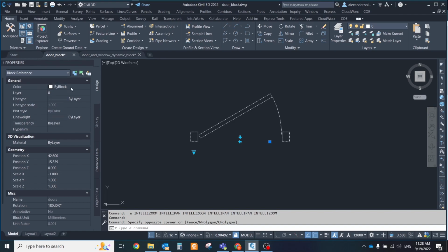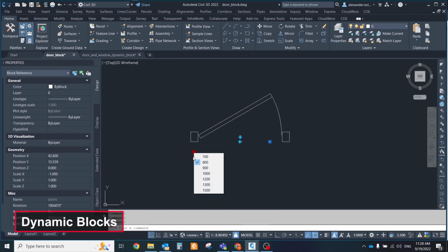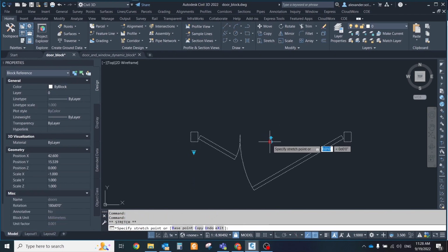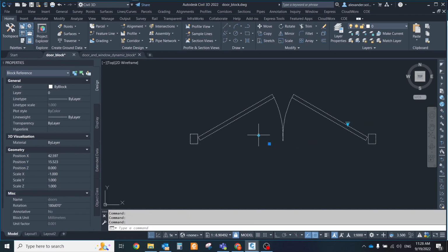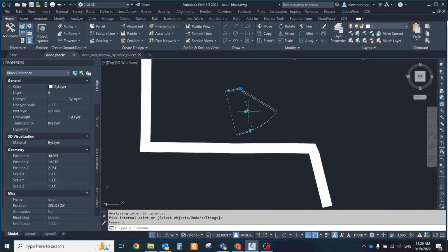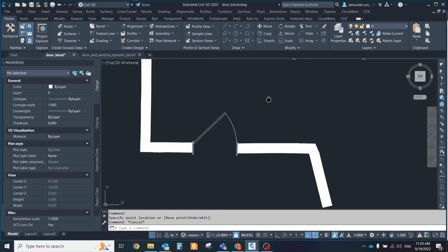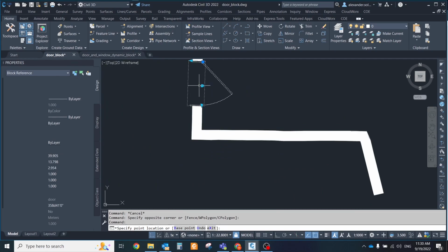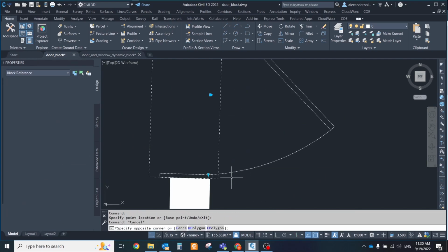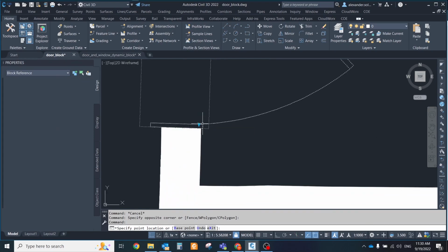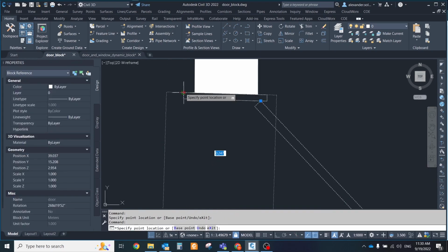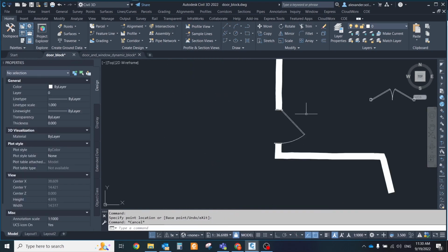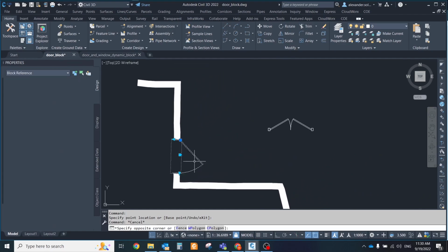After all main walls are finished, add doors and windows. I recommend using dynamic blocks for that. They are available in AutoCAD and BricsCAD. Dynamic blocks contain rules and restrictions that control the appearance and behavior of a block when it is inserted into a drawing or when it is later modified. You can add different visibilities, modes for blocks and rules for alignment according to the polyline. Below you could download a small example of the dynamic blocks.